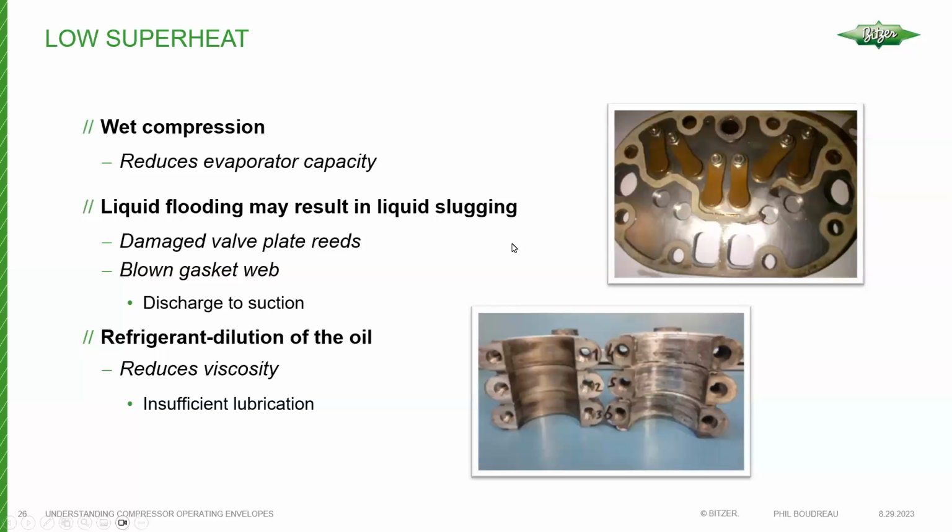So this isn't information we have to try and remember. You can find this in the technical literature. There's a guide that's specifically for torque ratings. It'll cover all gaskets, even joints that don't have gaskets. It might have O-rings. And again, like I said, bolt size, bolt quality. You can refer to the torque guide for a compressor, and it'll give you the correct torque.